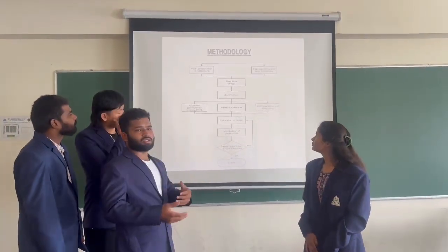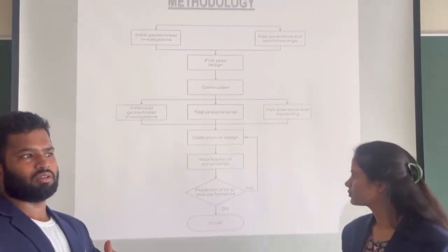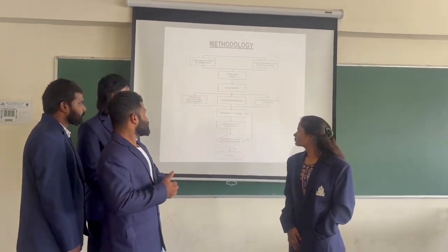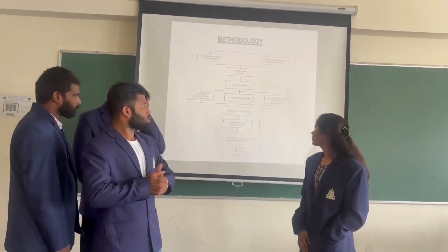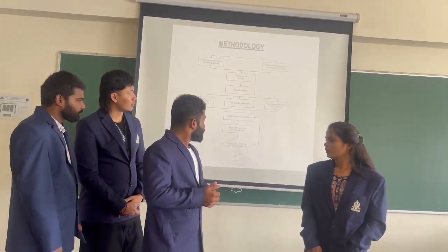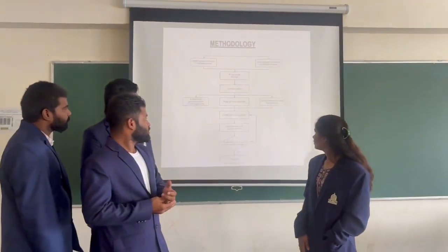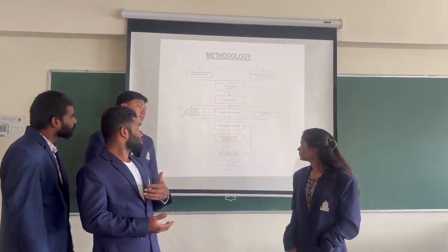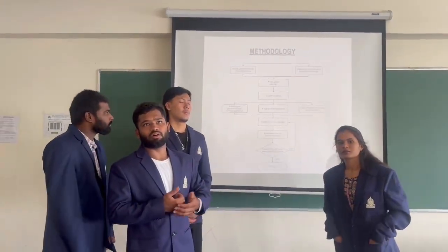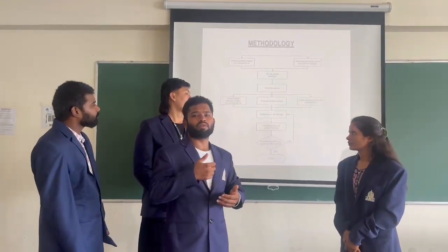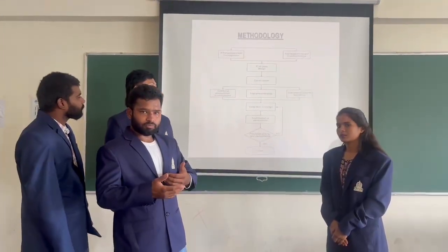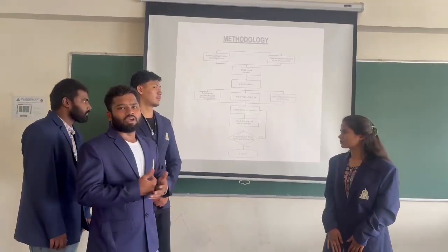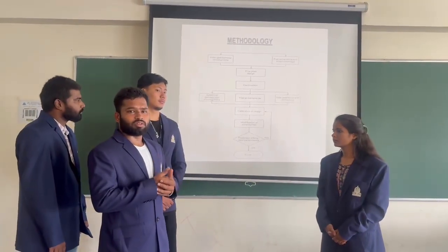Next it comes to the construction. The model should be constructed, followed by additional geotechnical investigations, trial embankments, instrumentation and monitoring. Then it comes to the calibration of the design. If any errors are coming, we have to calibrate the model's angles or the height.